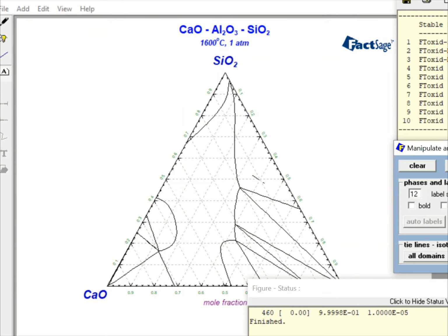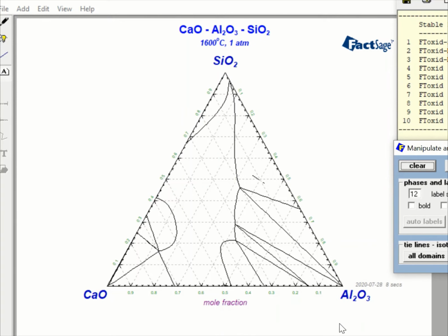Yep. And then once you have done, you see here CaO, SiO2, CaO, and then Al2O3 here. Okay, so it's a mole fraction base. And when you go through it, you have the stable phase mode, labeling mode, slag, and this tie line, slag plus mullite. Can you see? This is the mullite zone here, and this is slag. And this is slag plus SiO2, I'm sorry.